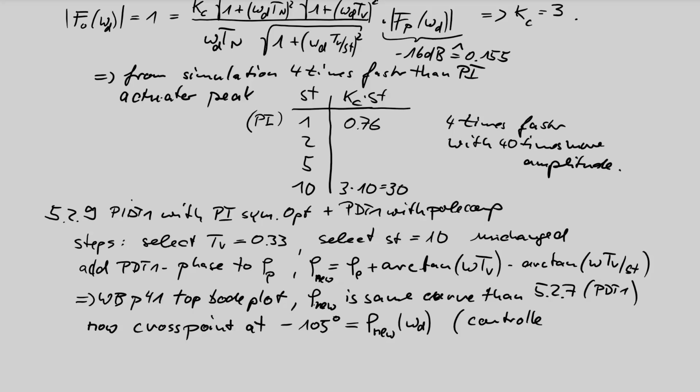It comes from the idea that the controller phase at omega d is minus 50. That is the selection in the symmetrical optimum. Note that this value is selected in the case that we have 60 degree phase margin. In the last project I present, if the process itself has an integrator, then I will show you that there is a clear relation between the selected phase margin and the selected negative phase of the controller at omega d.